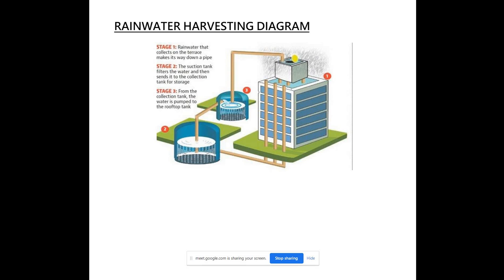Any rainwater harvesting system has three components: catchment, conveyance, and storage. There are two classes of rainwater harvesting systems. The first one is systems which collect roof runoff for household use, and the second one is systems which use in-field or adjoining catchment to provide supplemental irrigation for agriculture.